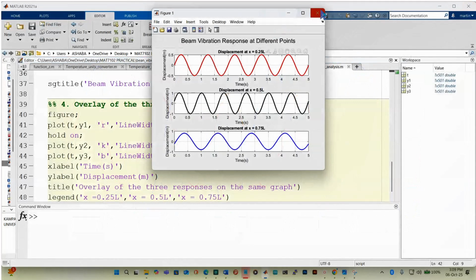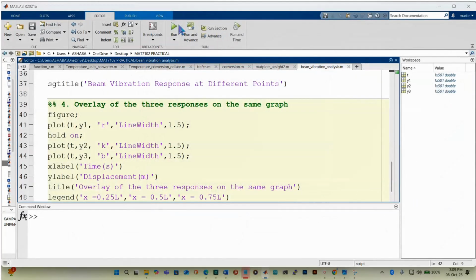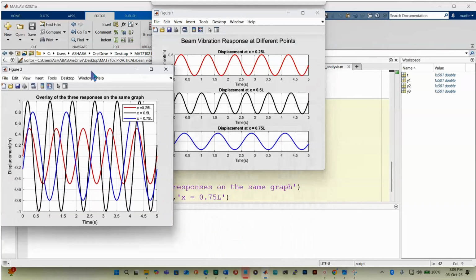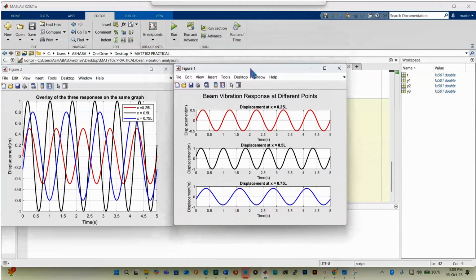So you can have these plots, first of all, one where you have everything on the same graph, and then another one where the rest are subplots. So this is the 3 by 1. So there are 3 rows and 1 column. So 1 occupies position number 1. Then this is now the 3 by 1 by 2.